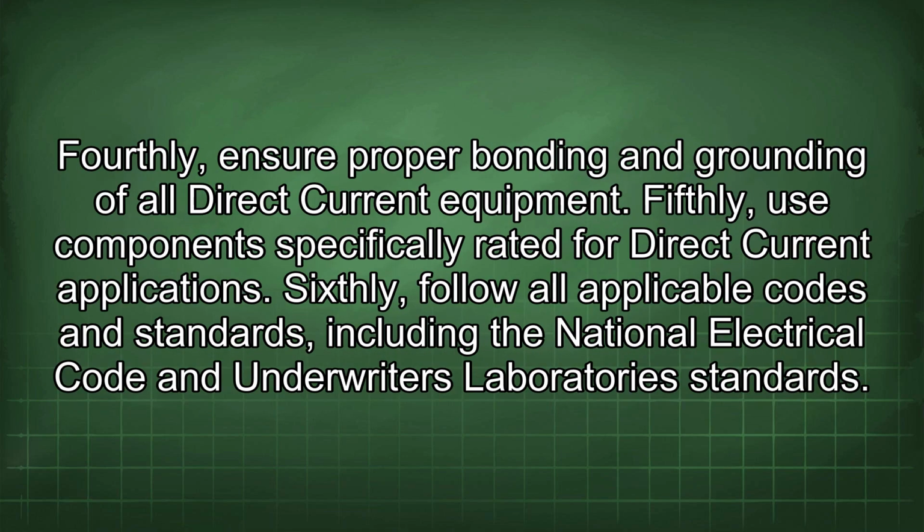Fourthly, ensure proper bonding and grounding of all direct current equipment. Fifthly, use components specifically rated for direct current applications. Sixthly, follow all applicable codes and standards, including the National Electrical Code and Underwriters Laboratories standards.